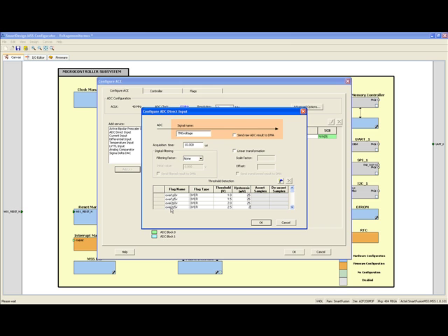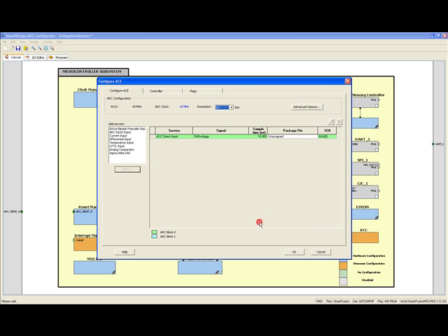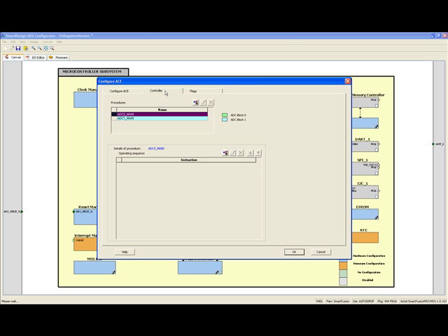This closes the Configure ADC Direct Input dialog. Next, going back to the Configure ACE dialog, click the pull-down on the Package Pin column and select pin W8, which is the package pin for the TM0 signal conditioning block 0 input. Now click the Controller tab of the Configure ACE dialog to set up the sampling sequence.